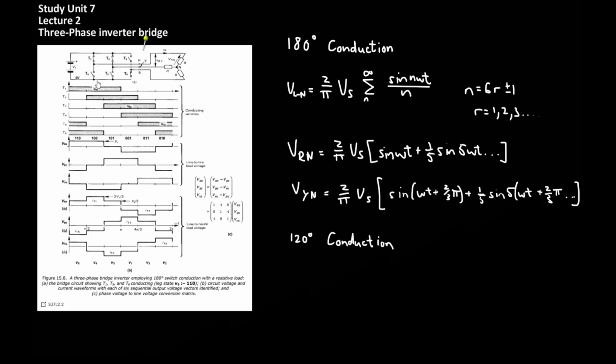So if we're looking at, for example, the switching phase between T1 and T4 with 180-degree conduction, the first part of the cycle, T1 will be on, and then halfway through T4 will turn on and T1 will turn off. With 120-degree conduction, there will be a dead zone over here to ensure that there is almost absolutely no overlap between the conduction of T1 and T4. The disadvantage of this improved safety margin is that the RMS output voltage using 120-degree conduction patterns is lower.